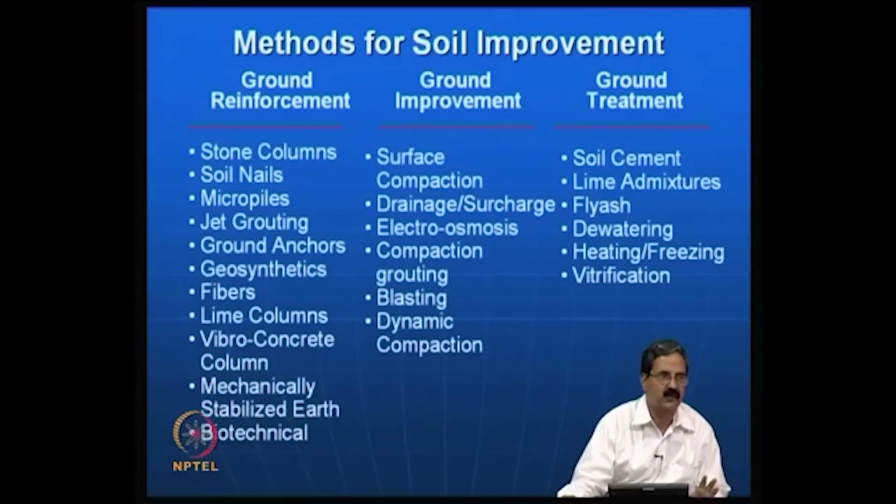One is called absorbed water, and then in the pore water there is some water, and then there is water that is adsorbed to the clay surfaces. So, if you want to handle them in a proper way together, electroosmosis combined with drainage is an excellent option. Then we have what is called compaction grouting. Compaction grouting is another technique that we use in many of the cases.